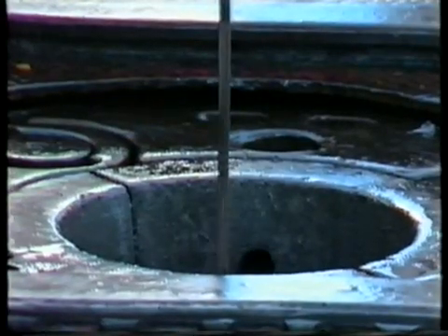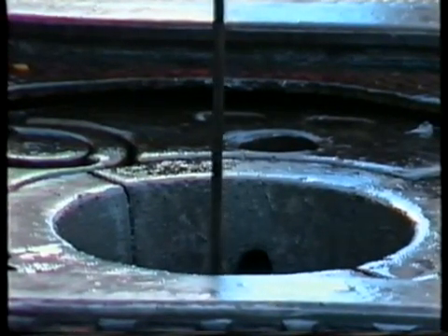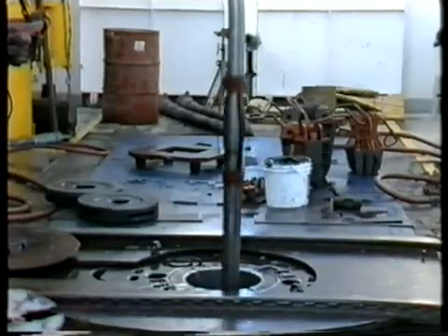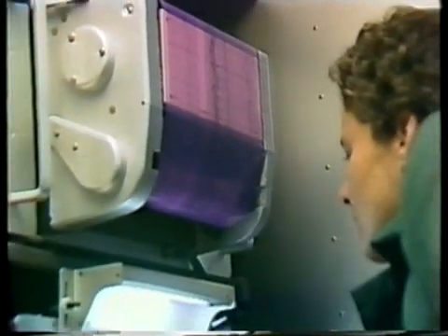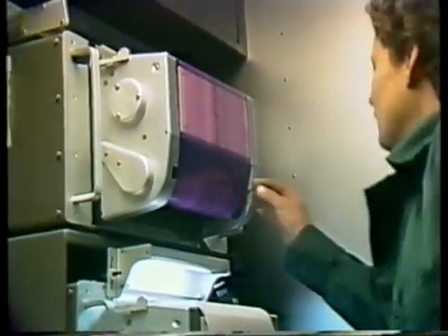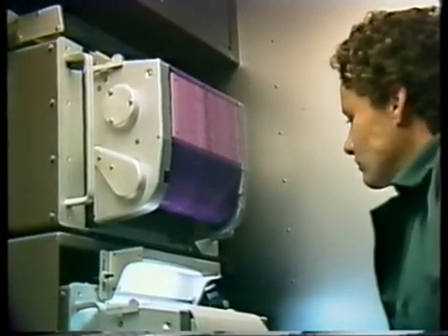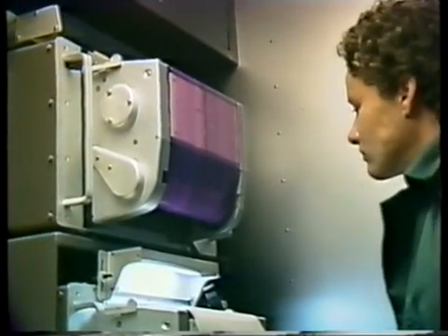When logging of the selected interval is complete and the logging string is brought to surface, essential steps still remain before the logging phase is considered complete. The logging engineer must check to determine that the logging tools functioned normally and responded accurately to downhole conditions throughout the run. A quality control scan of the logs is usually done to verify this.